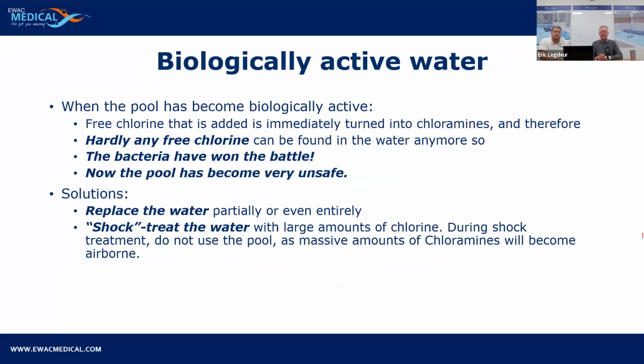But if there's so many contaminants in the water that all the free chlorine is consumed, that means that the bacteria have won the battle and the pool has become unsafe. It has basically become biologically active. There are some solutions to do that, but the best solution, of course, is to replace the water entirely and then start the whole process over. As I've said, you will get a copy of this presentation, so you have more reading time when you have received it. Next.